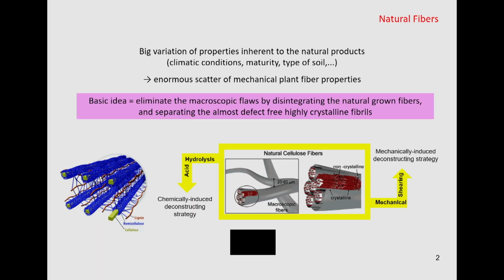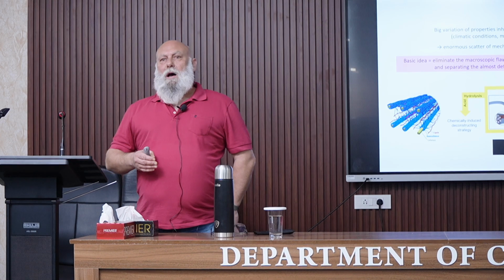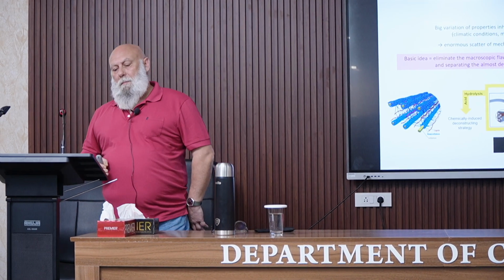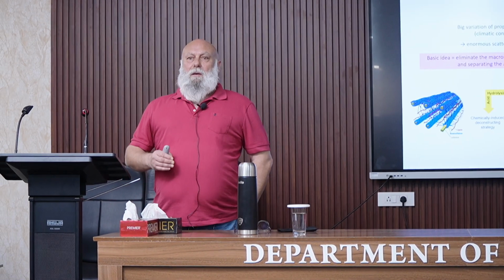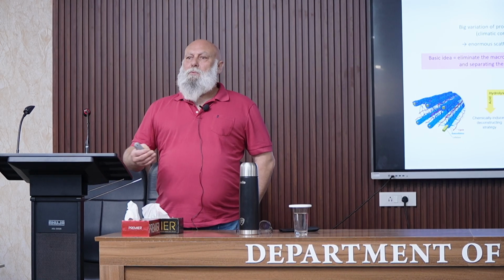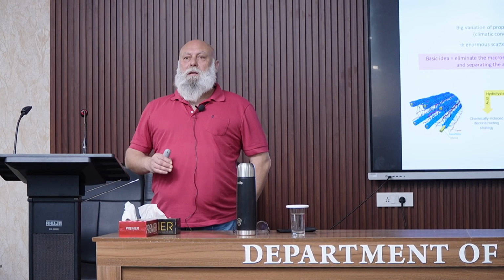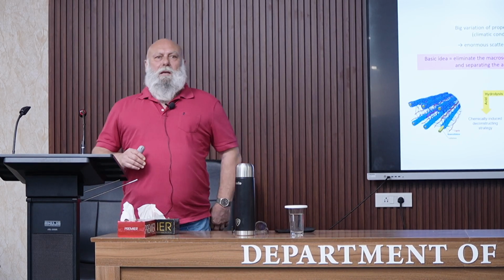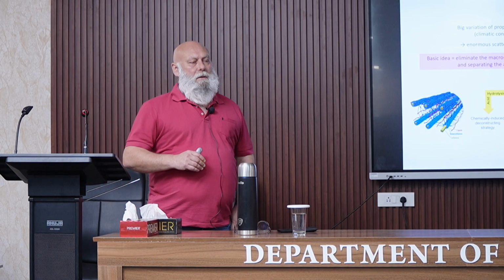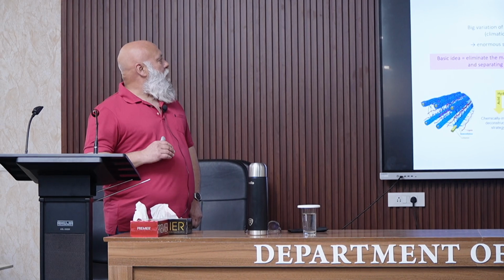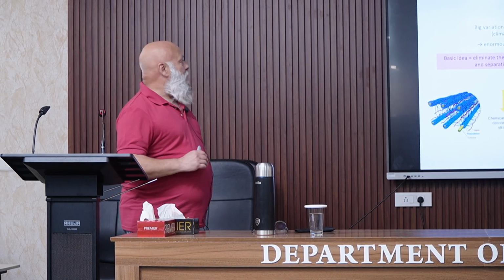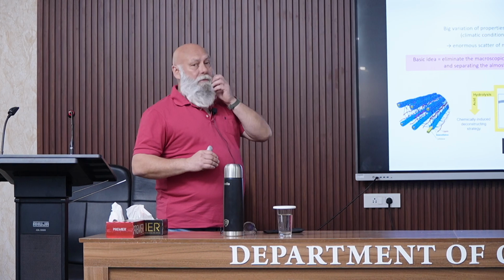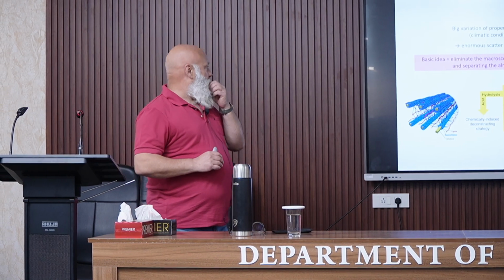So we have seen yesterday that there are some limitations in the use of natural fibers, mainly related to the hydrophilic character of these fibers that result in a poor adhesion with a hydrophobic polymeric matrix and a poor dispersion. There are also some issues that can be related to the thermal stability of these natural fibers, but another drawback is the big variation of the properties of these natural fibers.